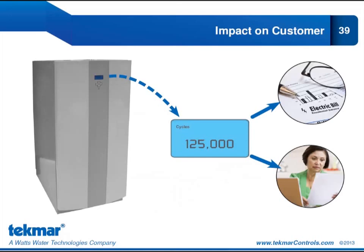What impact does that have on the customer? Well, we have excessive cycling of our heat pump. Our heat pump is turning on and off, on and off. It's not good for the equipment itself. It's going to have a negative impact on the efficiency of the heat pump, so we're going to see higher electric bills than we should, and that's going to lead to unhappy customers.